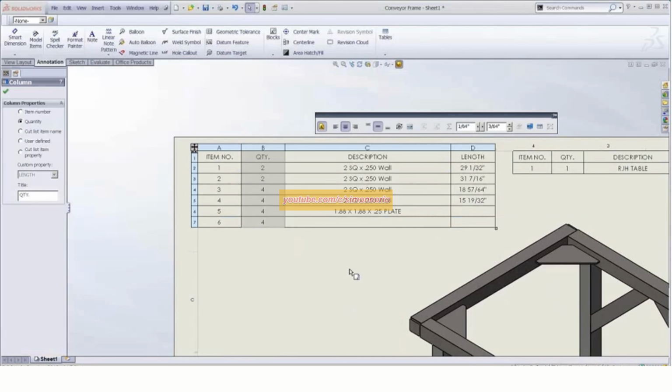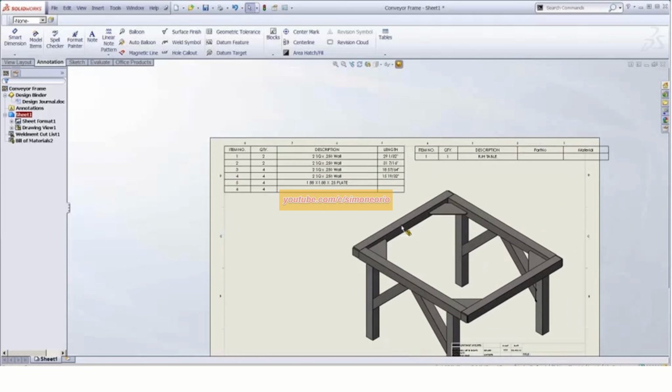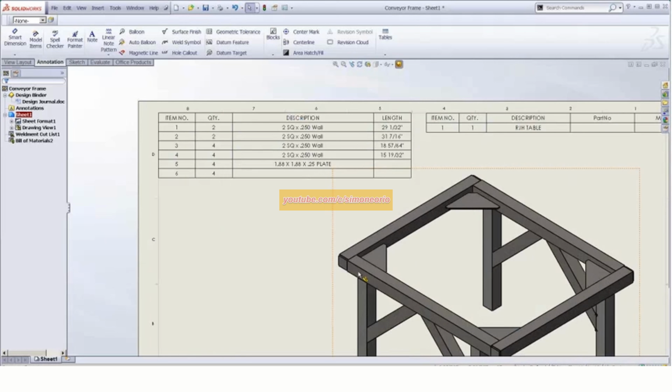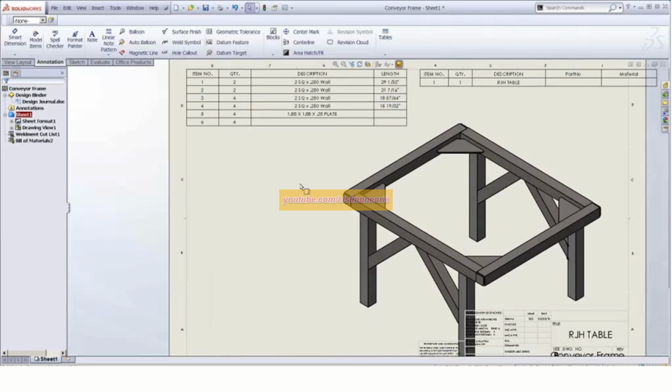And, again, over here, we've got our sizes. So our description here. Now, the one that's not being called out here, that's this plate, our gusset in here. So we do the same thing potentially in here, call out a description on that size. If I wanted to make it parametric, I'd throw those reference dimensions on there. That way it'd have a complete bill of material. It's way easier to get your part set up ahead of time and then come over to a bill of material than have a bunch of stuff missing out of it.